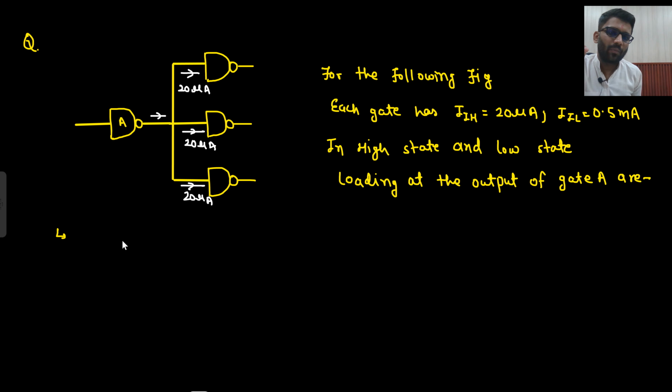So how much should be driven from here? So what is your IOH, output current in high state? That would be 20 microampere into 3. So that would be what? 60 microampere.